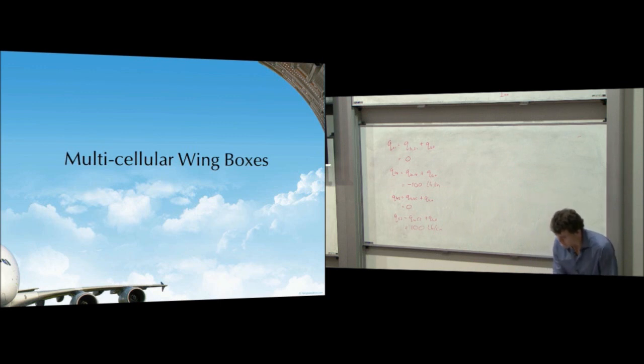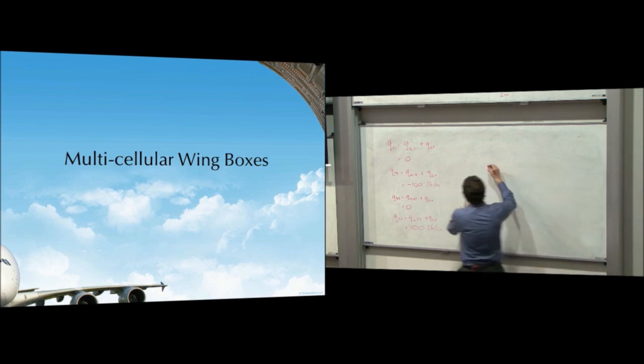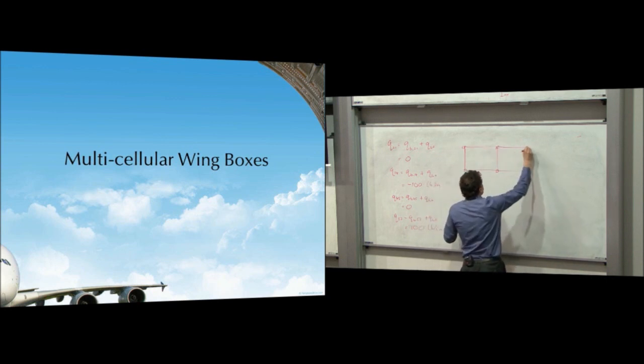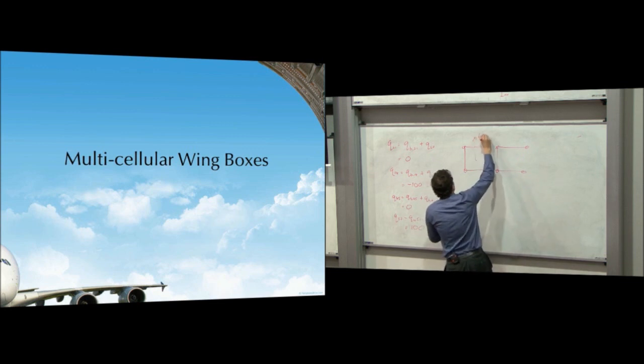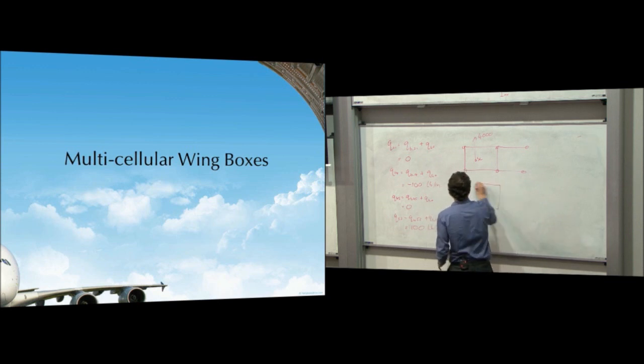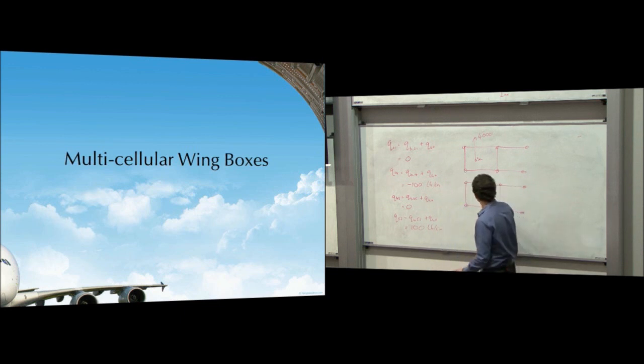The torque generates another set of forces. So what you've got to do is solve two problems independently. You've got to solve this problem where it's at the shear center. And you've got to solve this problem where it's 4,000 times an unknown distance.